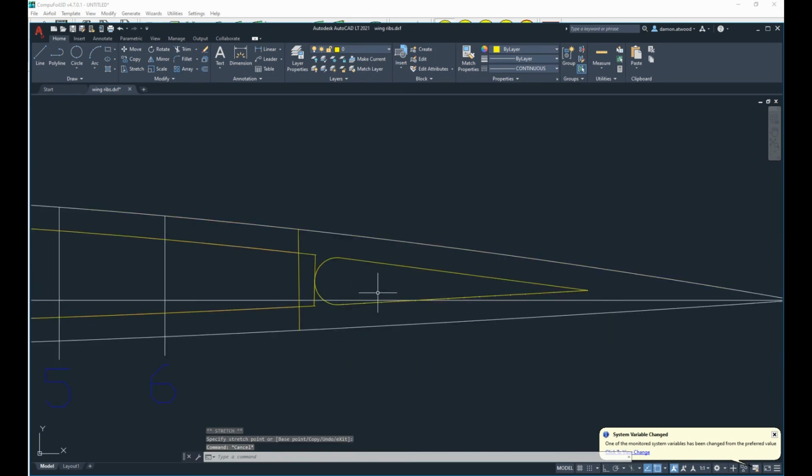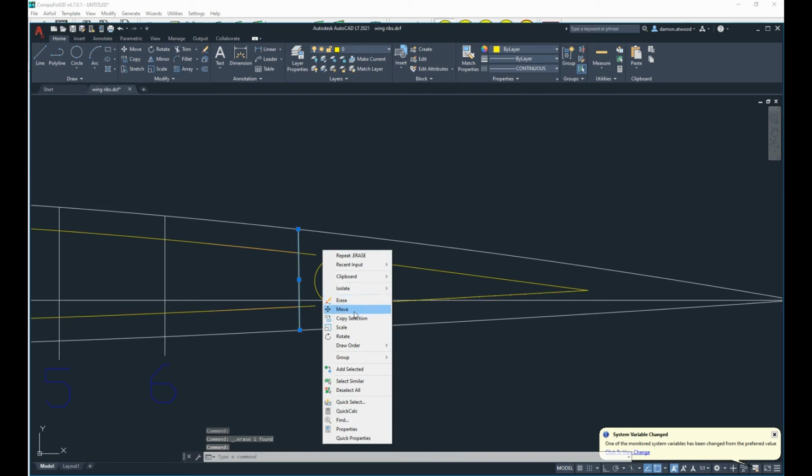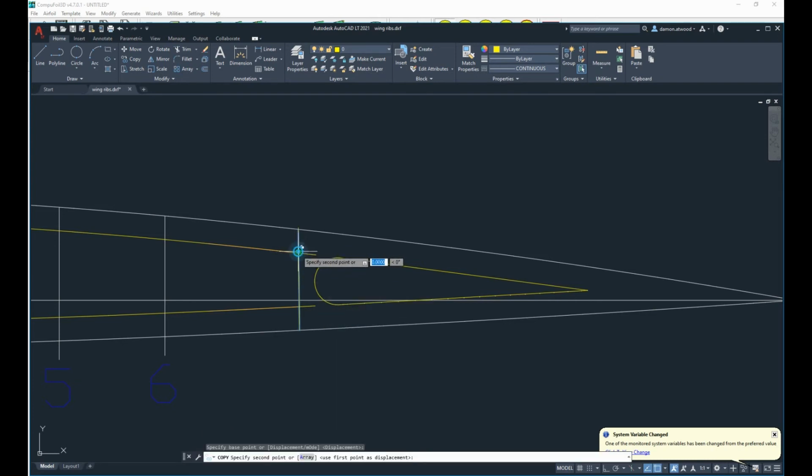So basically what he's going to do is, this would be his trailing edge stock right here. This would be the aileron part that he cuts out, that he laser cuts out, and then he'll skin this, and he'll taper this corner right here to give the radius. And actually, I probably will give him another reference line all the way out to here.